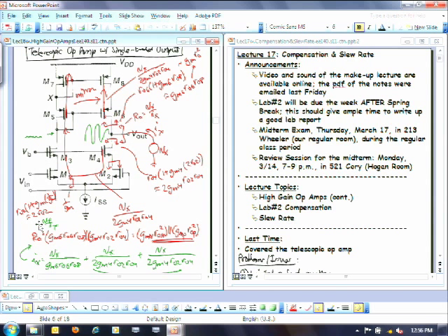If it's always opposite on both of these, then because this really looks like a resistor here, and that looks like a resistor there in the T model, this will be 0, regardless of what's happening at the top here. So you can think of this bottom part as being fully symmetrical and differential regardless of whether the top is or not. Now, both the top and this have to be fully differential and symmetric in order for you to divide this into a half circuit. That's why we don't divide this into a half circuit. But we can still say that the AC small signal voltage here is 0 when you're putting a fully differential signal across those two inputs.